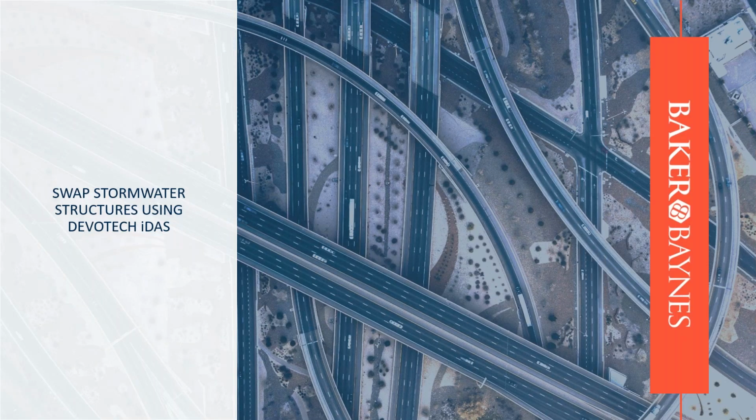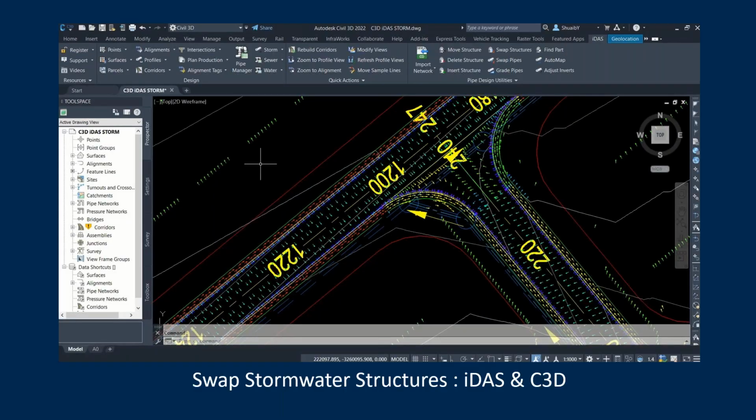Now, of course, before you go and do that, it is good practice to go and label and swap your structures first, but I thought I will just keep it with the flow, right? So generally what we do is we would swap the structures first. We will rename them depending on whether it's a curb inlet, a manhole, junction, whatever type of pipe network you're doing, you give it uniformity, and then we would normally do the profile section. If you do the profile view first, that is fine. And that is what I've done here, because you can still go and swap the structure. So I have kind of swapped the process around a little bit, no pun intended, and you will see that you will come to the same result.